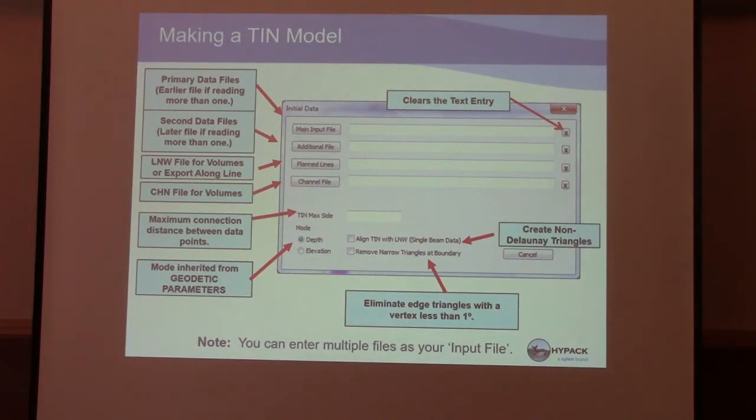That's all it is. It's going to take the first point in the file, and it's going to say, I'm standing right here, and all of you guys are XYZ data points. How far away can I connect? If I've got a 50-foot radius around me, I can connect to a bunch of you. If I've got a 5-foot radius, I can't connect to anybody. So how far away can I look for points? Let's assume the 5-foot radius, and we're all XYZ data points in the room. If I've got a 5-foot radius, who gets thrown out?